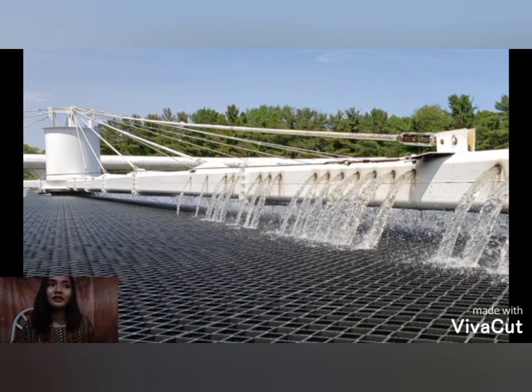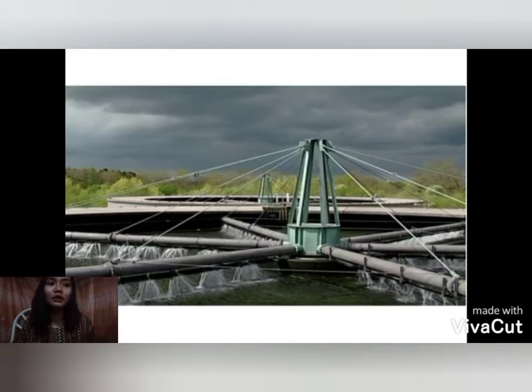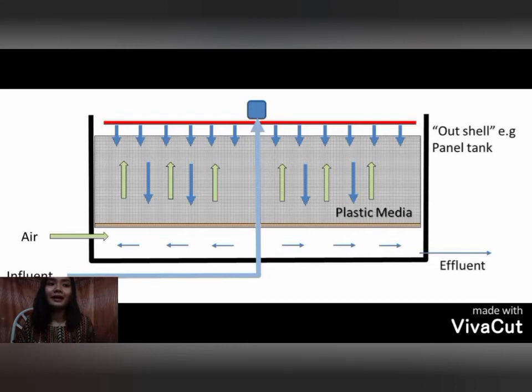Overcoming these limitations is done with modules of corrugated plastic sheets and plastic rings that offer larger surface areas for slime growth, with 90 square meters per cubic meter of bulk volume and greatly increased void ratios. So the materials are lighter than the rock. So you can just use plastic sheets rather than rocks if you would really like to overcome those limitations, so that there is no problem with the trickling filters.